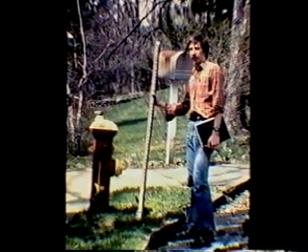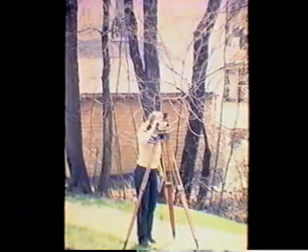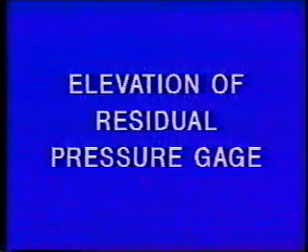Usually, for example, manhole elevations are known. So you can shoot the elevation knowing the elevation of a nearby manhole cover. And this will give you a great deal of accuracy, because it's kind of silly to measure the pressure to within an accuracy of 1 psi, which is about 2.3 feet, and then add it to an elevation which is only good to say plus or minus 20 feet. So you'd like to get the elevation to an accuracy of plus or minus 3 feet if you're going to use these results for model calibration.